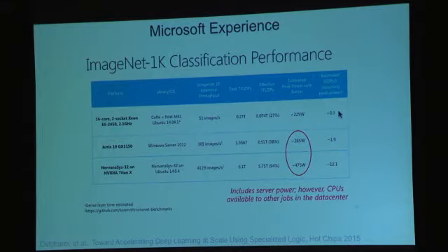This is basically GOPS per joule on the CPU, on the FPGA, and on a Titan X. And also, I don't know why they're charging a Titan X with 475 watts. It's a 250 watt GPU, and that counts the voltage regulator and the RAMs. But even so, it's on the order of a factor of 8 more efficient.